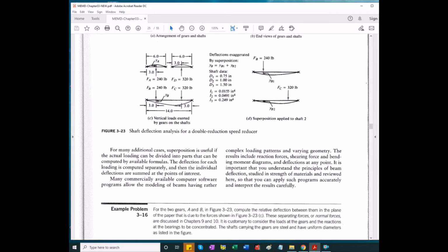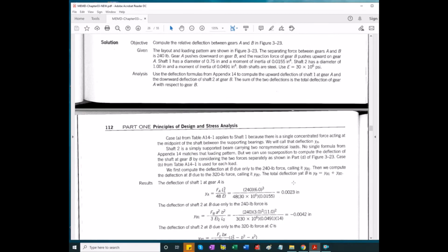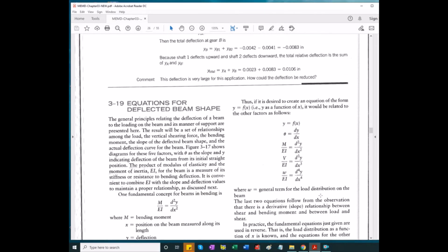At maximum deflection, slope is 0. Depending on the support, here simply supported, so we have possibility of rotation of the shaft. Cantilevers are different. There's an initial condition: no slope and no deflection at the support, assuming you have an incastration here, free end here. And again, successive integration, it's like going in reverse.